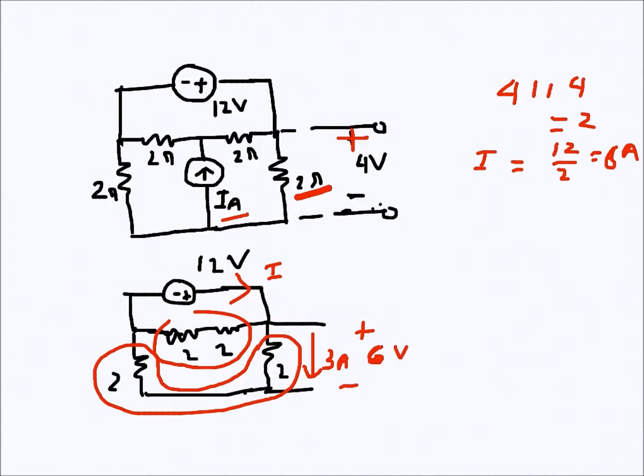So now we still haven't considered the current source, because we are applying just the voltage source effect. So if we consider the current source, we need to have a 2 volt voltage drop in this case, so that the final result is 4 volts in this direction. So due to the current source, since this is 2 ohms, to have a 2 volt drop we need just 1 ampere current. So a current of 1 ampere needs to go the other way, this way. That's what it has to be. So this information we will use to find the current.